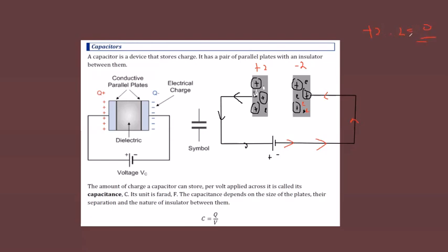That's why we don't say that a capacitor stores electrical charges. We say the capacitor stores electrical energy. Because if we say electrical charge, but there is no net charge, if it stored electrical charge, then the number of charges or net charge should increase. But the net charge is 0, so it shows that it is stored electrical energy.